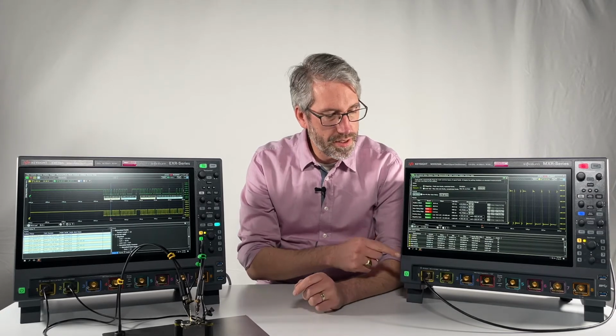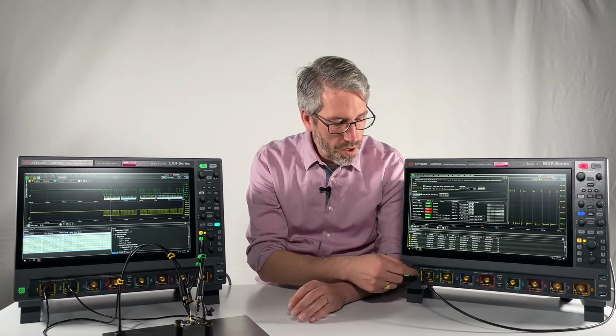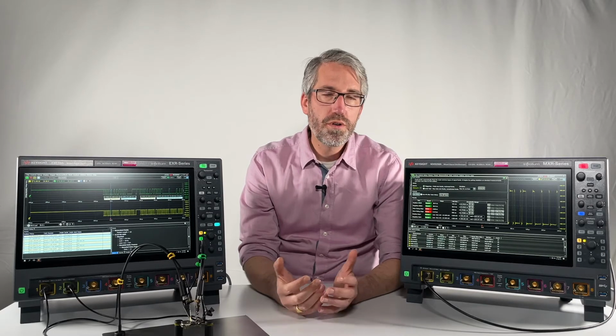And the good thing here on this scope is you can do that on one single channel, but you can do it also simultaneously on all 8 analog channels. This can be really helpful when you work with multiple input, multiple output, so-called MIMO designs, or just in general when you're probing a signal and you want to see if this signal is generating any spurs, harmonics or elusive signals which are unwanted.